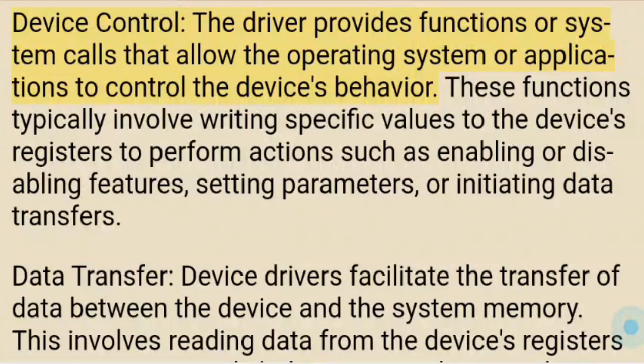Device control. The driver provides functions or system calls that allow the operating system or applications to control the device's behavior. These functions typically involve writing specific values to the device's registers to perform actions such as enabling or disabling features, setting parameters, or initiating data transfers.